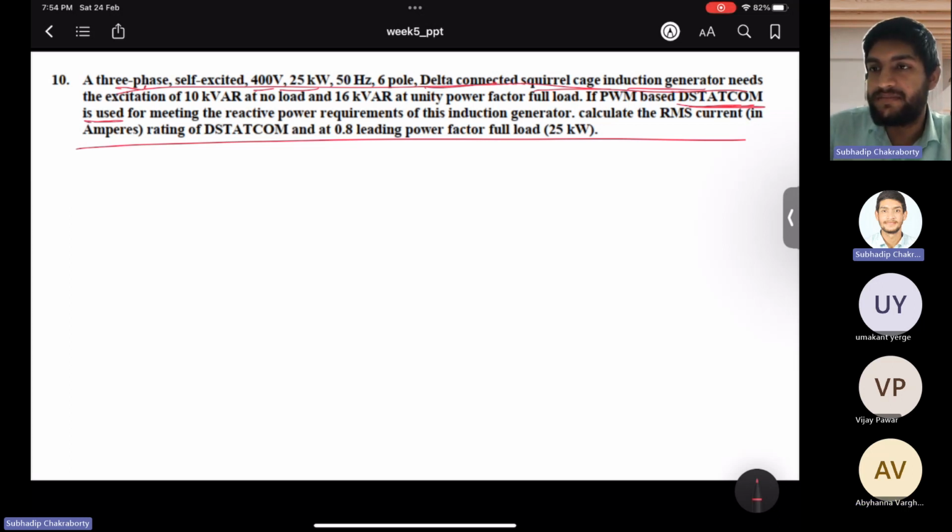In this case, you need to have some battery connected at the DC link, because initially, who will charge the DC link? How does the DC link charge? The DC link charges through the body diodes of the voltage source converter IGBTs. But in this case, the inverter needs some DC link voltage at the starting. Please understand, for the DSTATCOM, which is nothing but a voltage source converter, to be functional and provide all the features, you need to have some DC link voltage sitting there.